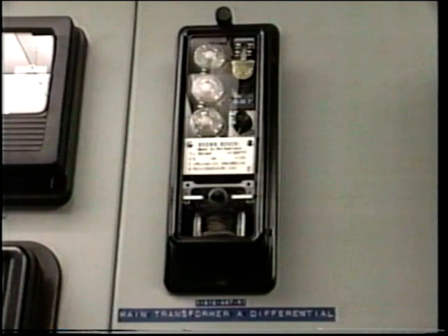Internal faults occur as a result of insulation failure, which creates a short circuit path between phases and often to the grounded iron core. The heavy fault current flowing can cause serious damage to the windings and even burn the core itself. If an internal fault does occur, the transformer must be immediately switched out of service and isolated. Differential protection provides the best protection against internal faults. And we'll be discussing this in detail in the next segment.